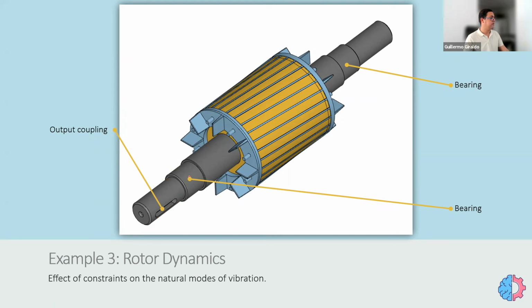Here we have bearings, and we know that they allow the rotation and only fix the displacements. It depends on each FEA tool how you get to this behavior, maybe with a hinge constraint, maybe with a remote point connection. There are many ways to achieve it, but it's very important that we model it as realistically as possible.